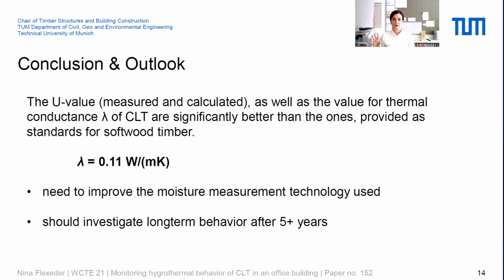This was roughly 1 to 2 years after this building was built, so quite new, and we do assume that moisture content is probably going down with the years, and we are expecting to get different results in a few years. Other than that, we're still working on the technologies to improve moisture measurement in walls with very highly fluctuating temperatures.